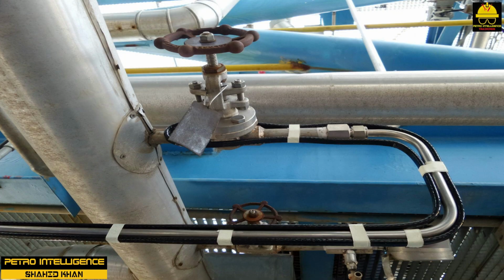The general practice involved with steam tracing includes wrapping copper tubing around the process pipe and covering it with heat transfer cement or insulation. Hot oil tracing systems are used when the process fluid is hotter than the plant's steam system. Low-pressure steam or hot oil is passed through the copper tubing during operation. This procedure is often used to winterize a unit when temperatures are expected to drop below freezing. A negative aspect of steam tracing occurs when the copper tubing sweats under the insulation and, as a result, traps moisture next to the piping.